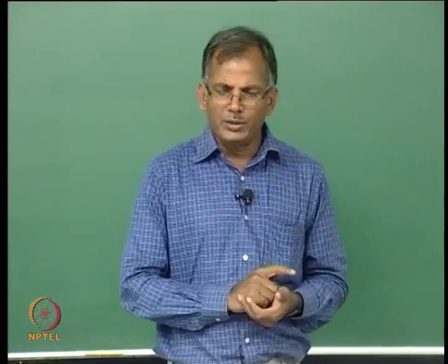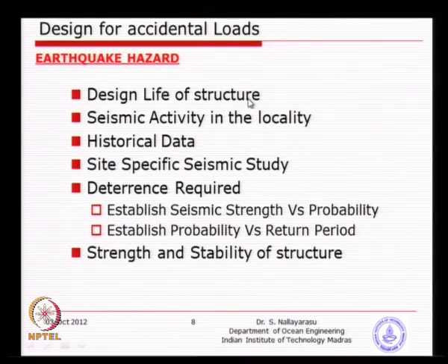So, in earthquake hazard, what we are looking at is basically the design life of the structure, the seismic activity in the locality wherever you are constructing your structure, and historical data of what was happening over the last few hundred years, because this will give you an idea of what needs to be designed, since this is an unknown hazard, very difficult to design for.